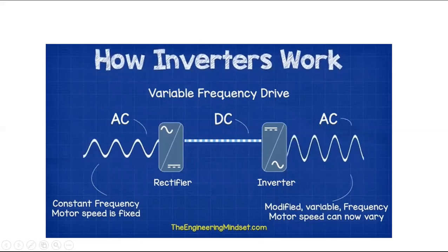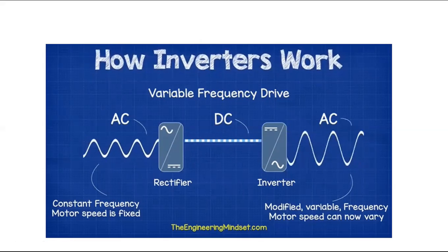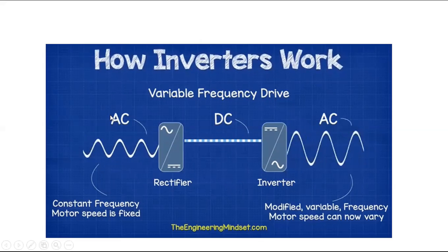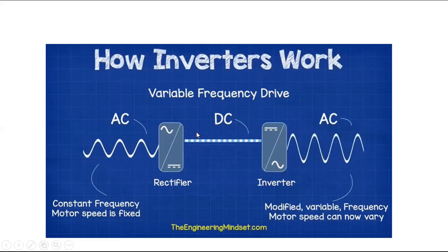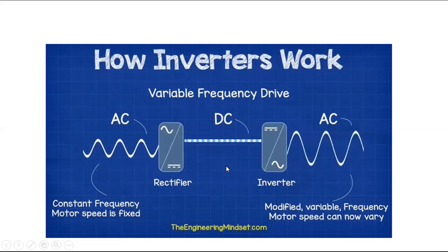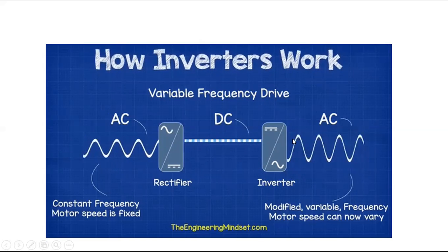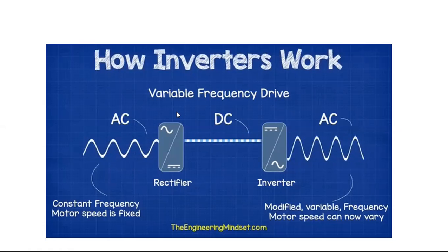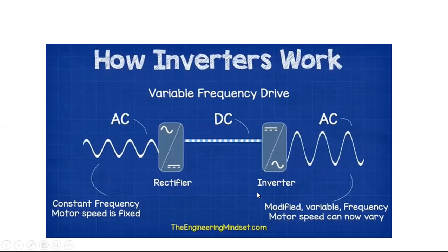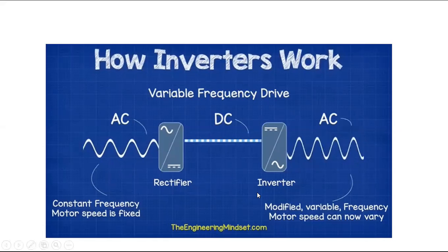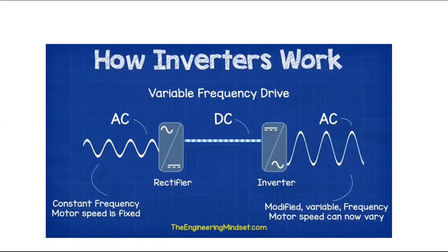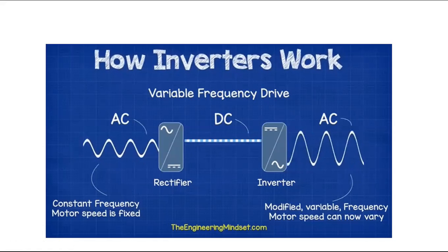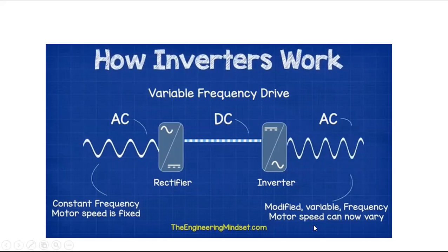So power electronics is a branch of science which deals with the control and conversion of electric power. An inverter is a power electronic circuit which converts fixed DC power, when we say power, DC current and DC voltage, to variable AC power at different frequencies. This point is important. Okay, at different frequencies. We cannot say directly DC to AC. Fixed DC power to variable AC power at different frequencies. You can see the frequency is changing here of the input AC circuit, right?